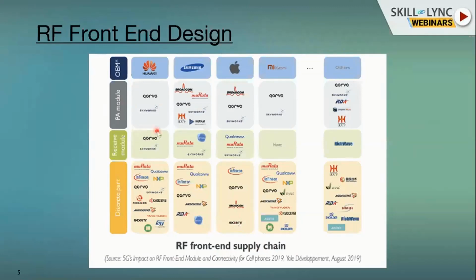This particular slide talks about how you actually choose, because you are going to design an RF front end or the system design. You are not going to build everything yourself. You are going to acquire all those components, and while acquiring them, you should list out, before purchasing, what the behavior of each component has to be.